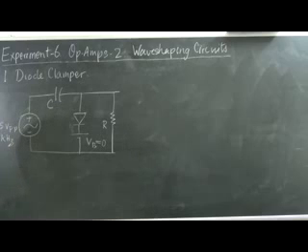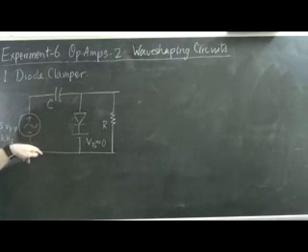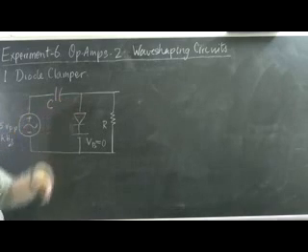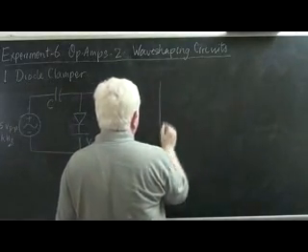So the capacitor voltage more or less stays in pace with the supply voltage, and hence this terminal is equal and opposite to this terminal, and the output remains 0. So let's just plot the input versus the output.